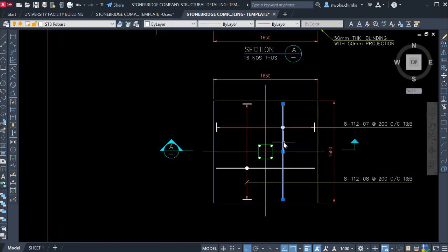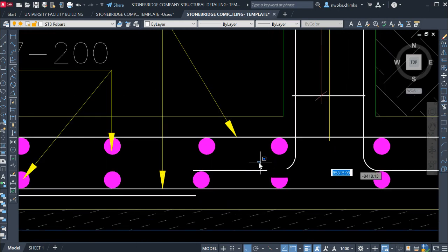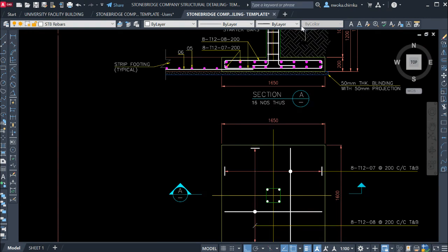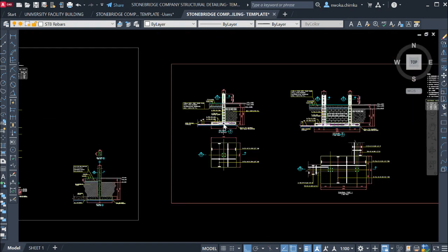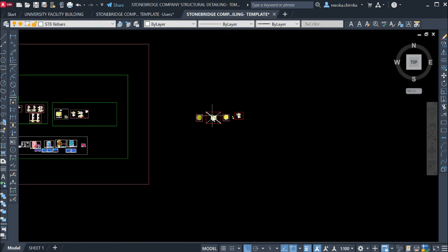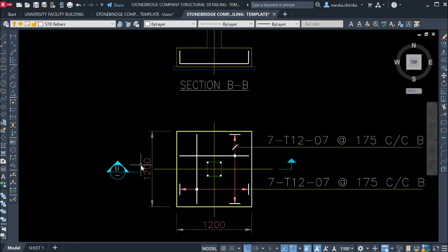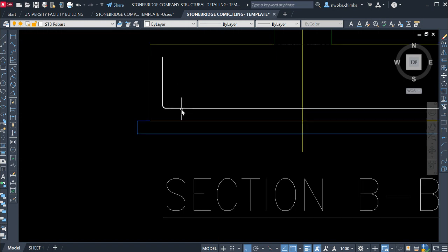this, our vertical reinforcement here as a circle dot, because that cutting line affected this reinforcement. So if you now view it from the way this arrow is, you will see it as a dot, as you can see it here. So right now we have to also apply the same principle on this other one. If this cutting line cuts through this footing, it will affect this reinforcement, which we will have to see as a circle, as you can see it as a dot.